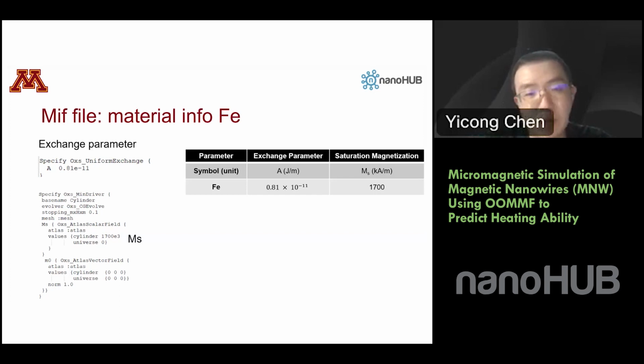But for example, if you use a cylinder, you want the mesh small enough to actually show the rounded circle, because we want to subdivide the sample finely enough to maintain a circular shape.